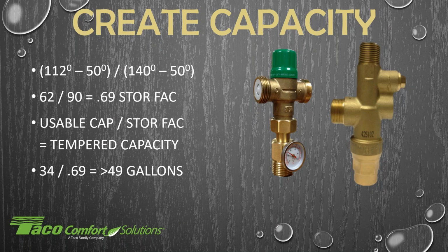I remember quite a few years ago when some NAECA standards came out creating efficiencies for water heaters, which meant the insulation jacket got larger. Some homes that had a 40-gallon water heater shoehorned into a closet space could not fit that same 40 in there. You had to put a 30 in instead, and now all of a sudden we started running low. Mixing valves can help in that respect. So that's one thing you can do, is add more capacity by adding a mixing valve.